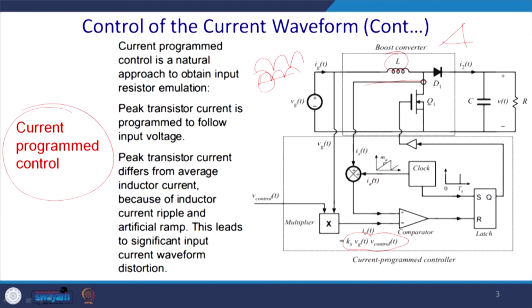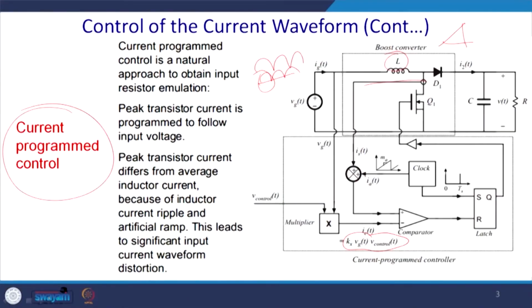Then you ask the current to ramp up until the highest boosting rate, so for this reason the duty cycle is fixed to some limit. This ramp will be compared with the clock. As long as the clock is high, you will get an output here.